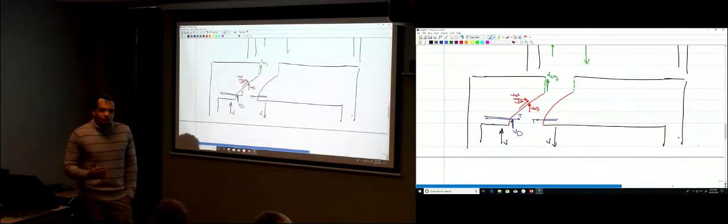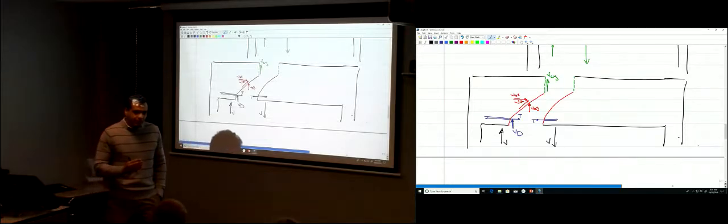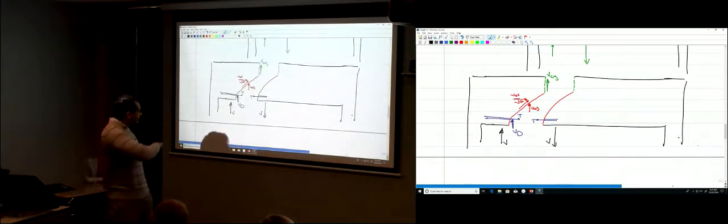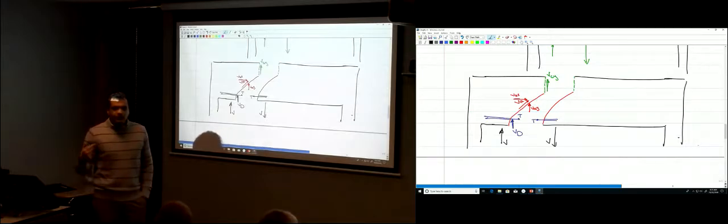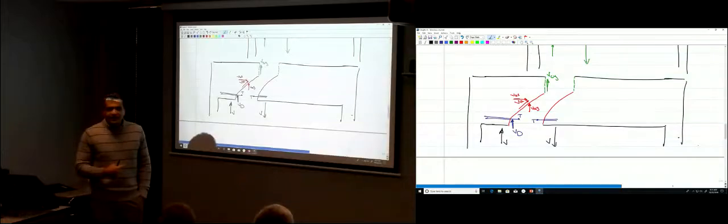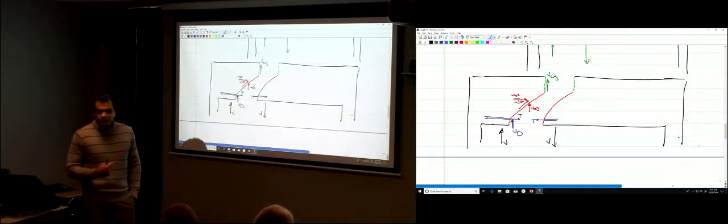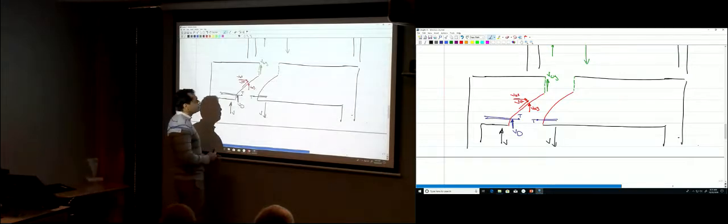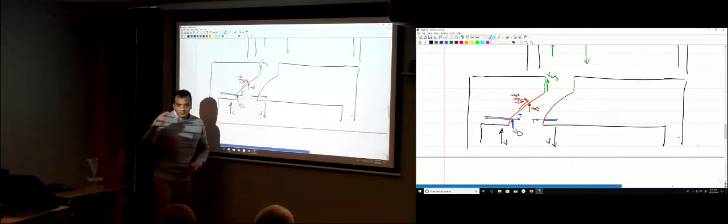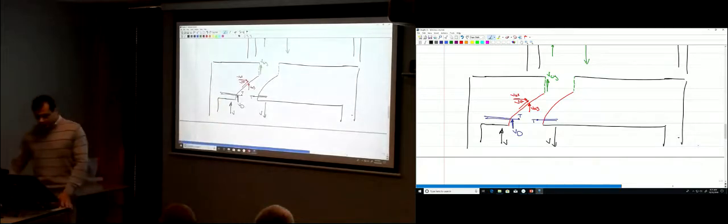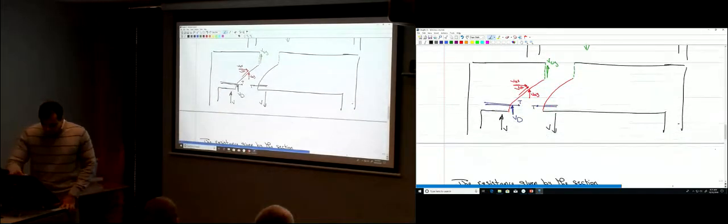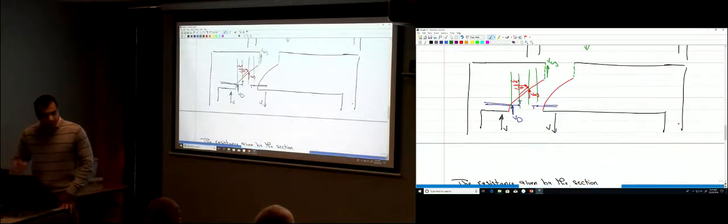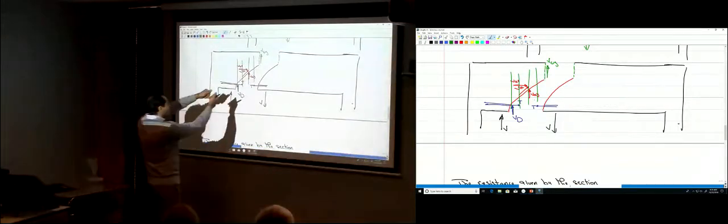What we're going to do is find some type of reinforcement for that line to prevent it from breaking, and that's the shear reinforcement. So what type of shear reinforcement will we provide? The stirrups. Stirrups go like this, so they hold both parts together.